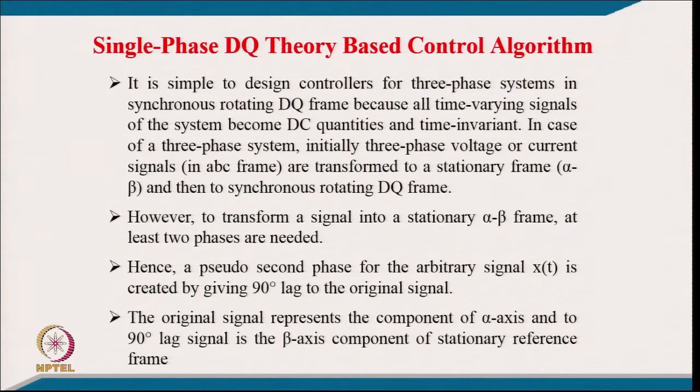Similarly, the single phase DQ theory is also modified to be applied for the 3 phase D STATCOM, and this is the typical explanation for that. It is simple to design a controller for 3 phase systems in the synchronously rotating DQ frame, because all the varying signals of the system become DC quantities and time invariant. That is the advantage of this DQ theory.